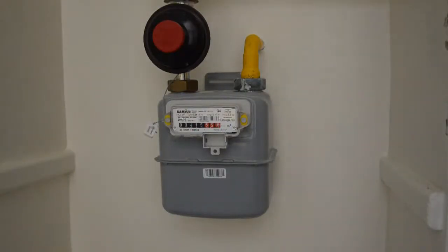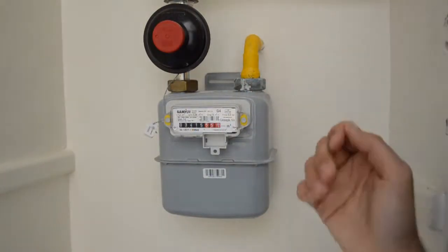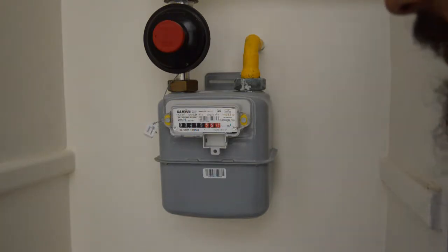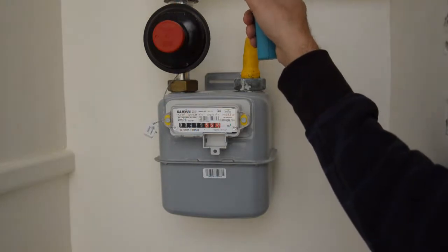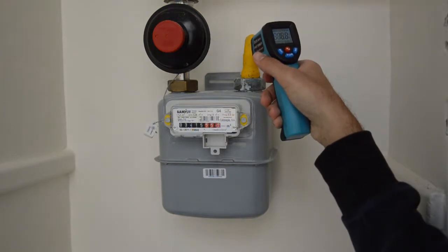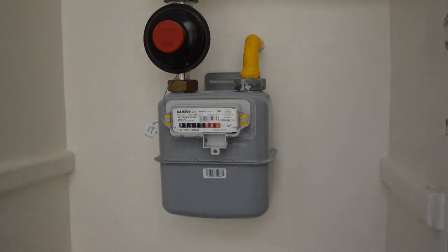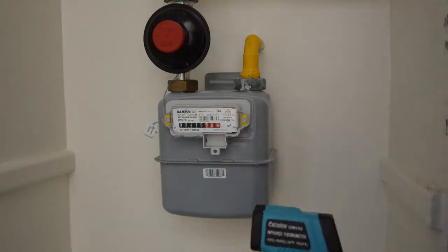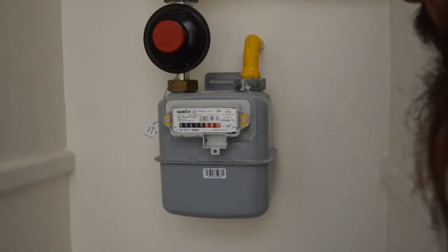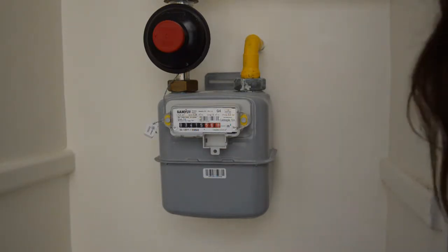One last thing we want to measure is the temperature of these pipes which bring the gas to the stoves, so that we can adjust the density of the gas, because of course to know the energy for each volume of gas we need to know the density of the gas. And so let's measure it. 17.8 degrees here and 18.2 here. So the problem is the pipe is not at the temperature that the gas is, but it's something in between the outside temperature and the gas temperature. But yes, I'll make a little adjustment.